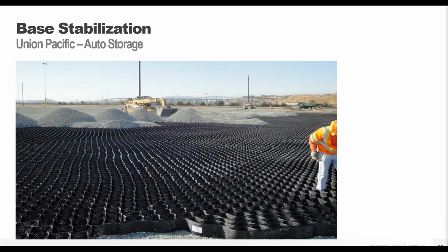So here you can see all of the expanded GeoWeb panels and the open graded fill being placed into those panels. As I mentioned before, it's easy to see how that installation process would go. So the workers would expand the GeoWeb panels, connecting every individual panel with our ATRA keys to create a continuous system that covers the entire area. And then the infilling comes behind them, filling in the cells from those large piles of stone. Again, you can use things like front end loaders, or you can get workers with hand rakes or shovels to push the stone in.